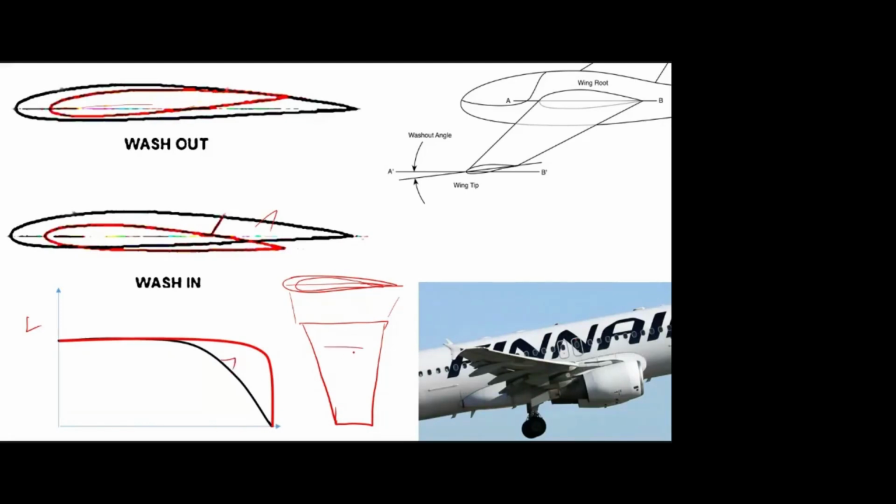Because here the area is decreasing, the lift also decreases towards the tip section. Also, there will be a side leakage flow that affects the pressure difference. So you will get this type of lift distribution curve. Is that clear? If you take just a straight wing without any twist, is that clear? Yes, sir. So here we are getting some loss of lift near the tip.